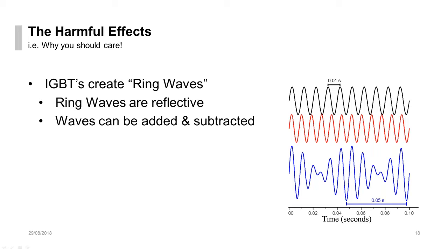Now, clearly, we started with something that maybe was only 500 volts above design. But when we add these waveforms together, we can now get to 1000 volts above design. Clearly this is going to attack insulation. It's going to cause damage to the motors. The magnet wire isn't going to be able to handle it. It also increases the heat within the motors and cabling. So this is high frequency, and it's therefore very high stress.